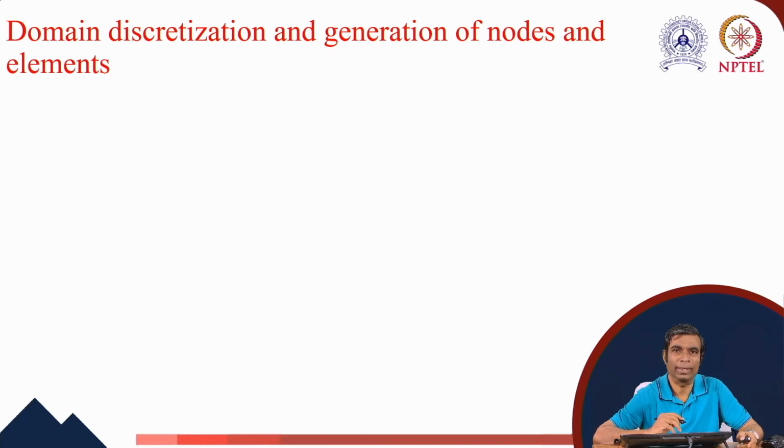As we have already discussed that the finite element method is an improved version of the variational method, we identify the finite element method as a discretization technique. By discretization, we indicate that we discretize the governing equations, the boundary and initial conditions along with the domain. So this domain discretization is also known as mesh generation. The generation of mesh is consistent with the Eulerian approach used in fluid mechanics. The governing equations in fluid mechanics are written at points.